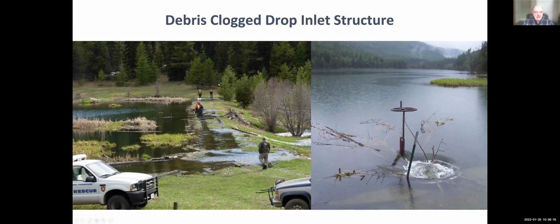But look at the vegetation. The vegetation's doing a wonderful job, right? Overtopping, and we're not really seeing a lot of erosion at this point because the velocity of the water is just not enough to start to cut down through the vegetative mat and start to erode the embankment. So having that grass cover, a nice, consistent, well-established grass cover, certainly is an advantage as well.